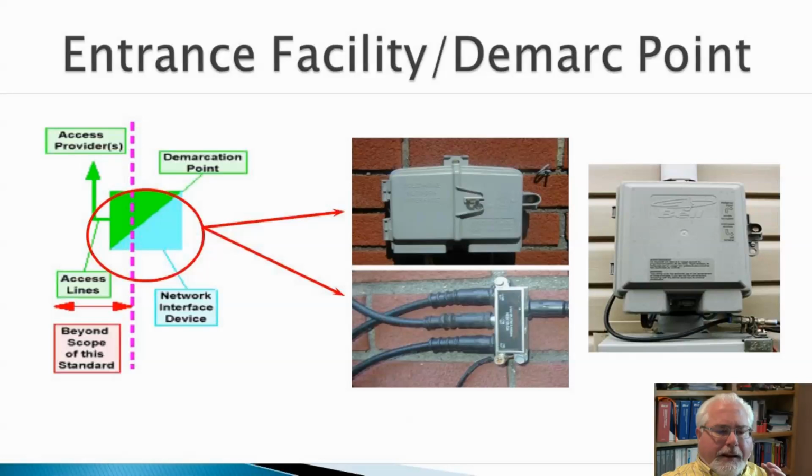And so we're going to find a route from this position into the home or building, or into the low voltage panel. And I generally tell contractors, as a general rule, always hide your wire. Put it in conduit if you have to. Don't leave it exposed on the outside of buildings, because people do stupid things like accidentally cut it, paint it, hang their Christmas lights from it, all kinds of stupid things. So always try to make sure your cables are covered up and not exposed, okay?